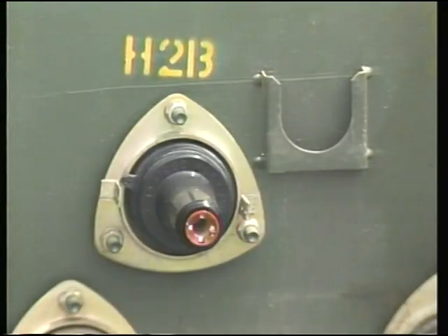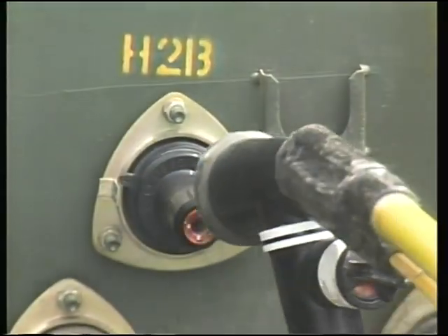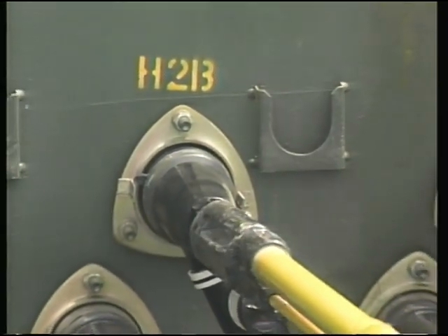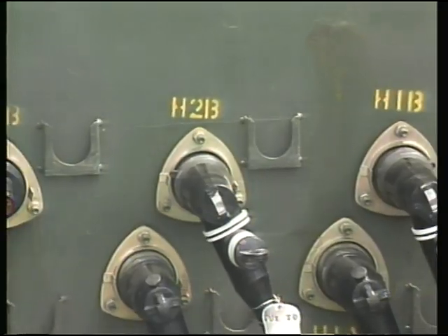Earlier in the program, we said that the environment in which a cable is used is one factor in determining the type of termination that's needed. Another factor is whether the cable is used in an underground, overhead, or URD application. In URD work, for example, insulated terminations are commonly used. An insulated termination is one in which the connection point between a cable and a piece of equipment is insulated. Typically, URD equipment has bushings that require elbow terminations. An elbow termination provides a fully insulated connection between the cable and the equipment.